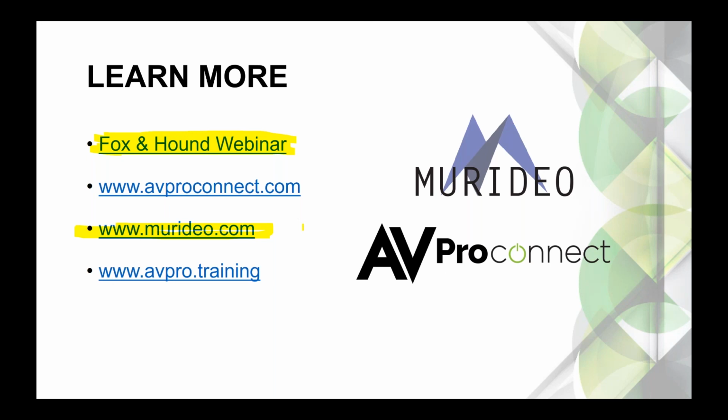Shielding is an environmental requirement. If you are not sure, especially in light commercial, if there's EMI or ESI emanating throughout a space, attic, crawl space, then it's best to use shielding. Sometimes in bars, sports bars and the like, I've seen issues where shielding was important, when there was a lot of neon signs. So shielding is more environmental. The minimum spec to get the 4K at the distances we quoted is a Cat5e. But again,